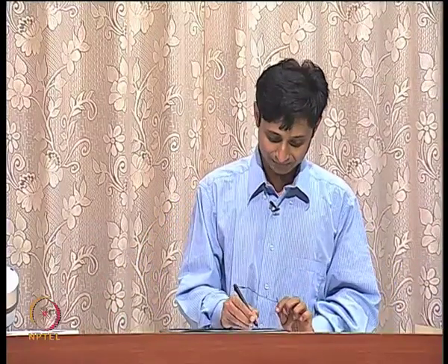So, I made a statement earlier which kind of gives you a hint. The capacitance is so large that the entire device looks more like a capacitor than like an inductor. What do you make out of that? What should be the metric? Well, you have got this thing called a resonant frequency, right. You put L and C in parallel, you have got a resonant frequency. So, below the resonant frequency, the device looks like an inductor. Above the resonant frequency, the device looks like a capacitor, right. That is how it is.